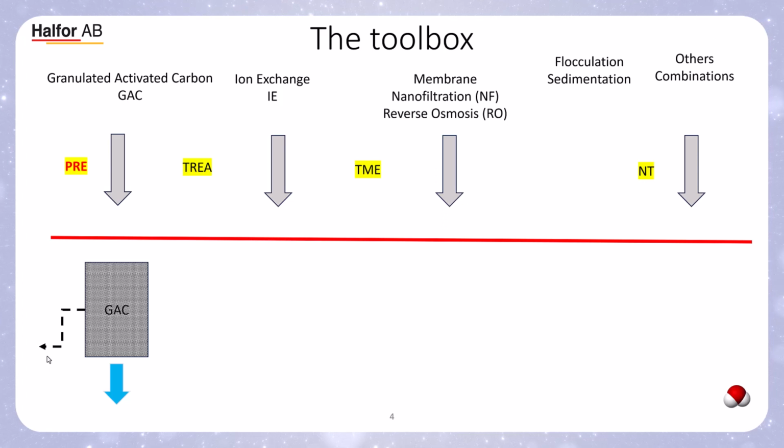And in worst case, I've known cases where you have taken an activated carbon and it took 1 month until it was saturated and needed to be replaced or recharged. Many times, most of the times, you find a carbon that will last you a year, maybe 5 years before you need to replace it. So the selection of activated carbon will be dependent on the water quality that will affect how your PFAS substances can be absorbed in the activated carbon.